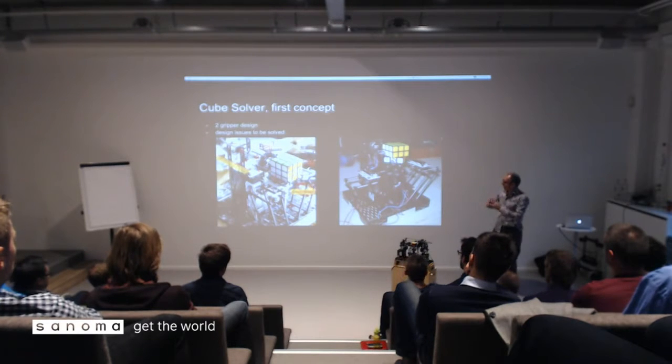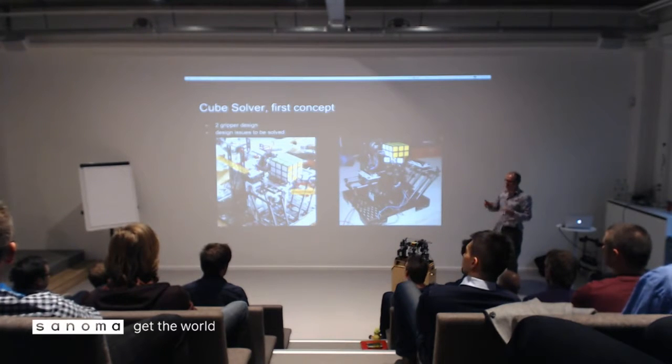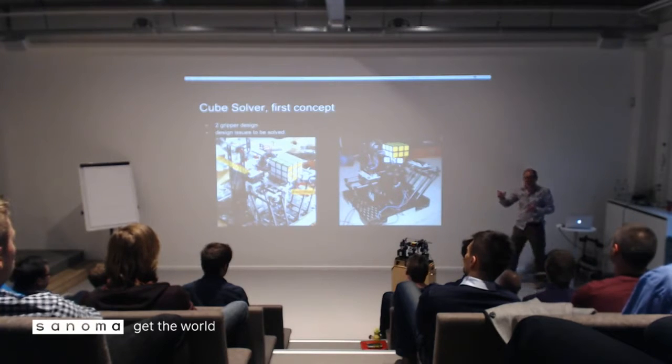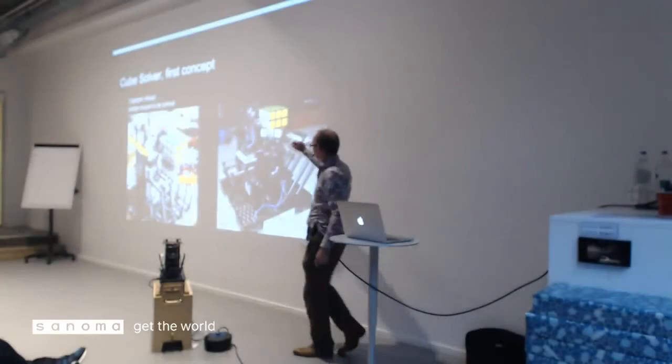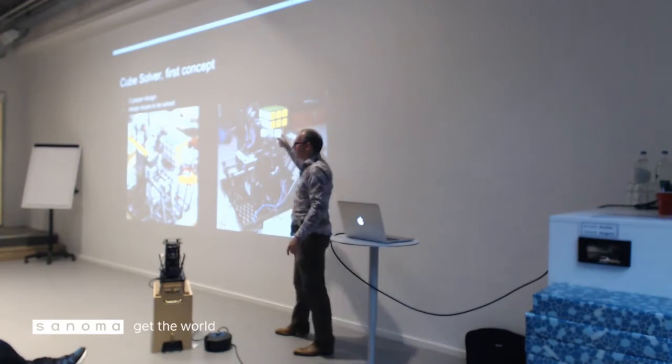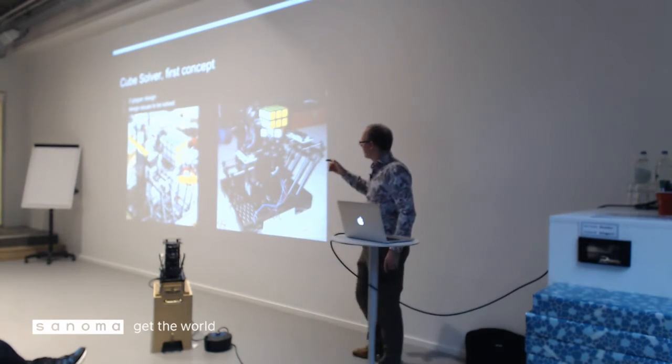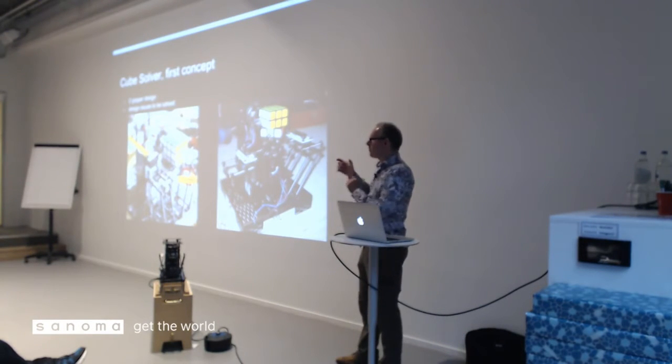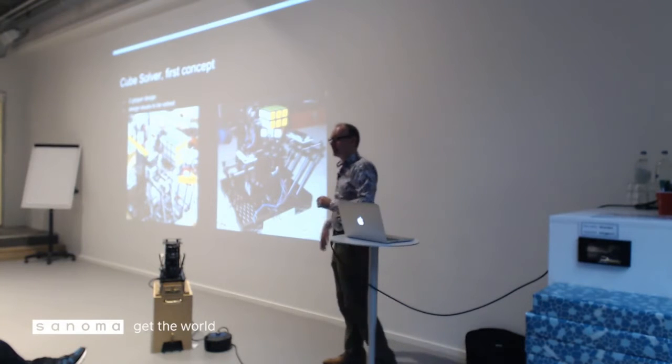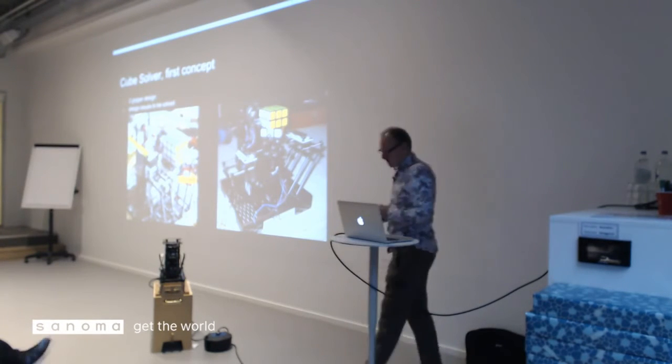Well, the table actually functioned quite well. That's why I reused it in the next concept. But as for the grippers, I was satisfied about the gripping technology behind. But sometimes only one gripper grips the cube, and if you take, for example, the left gripper there, if that's the only gripper which grips the cube, then it might be possible that the cube is not held in position anymore. Well, that's of course killing in this kind of purpose. So that's why